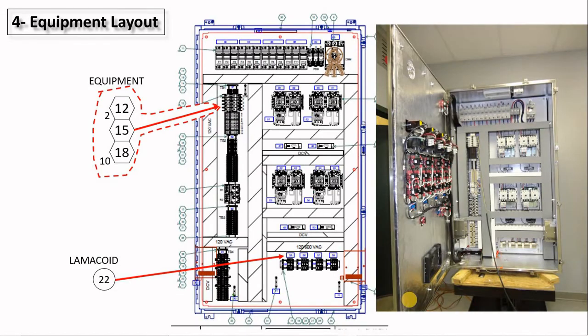Now if you receive a cabinet for review, you also need to check the clearance between your terminals and the raceway or the wireway. The wireway may be very close to this circuit breaker, but you have enough space for your wiring here. All the field wiring could be on this side, and on that side you have the 24 volt, and so on.